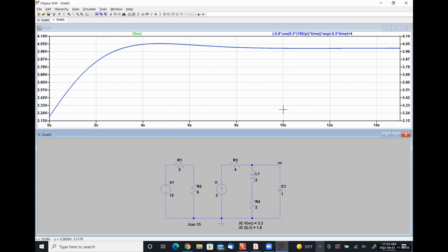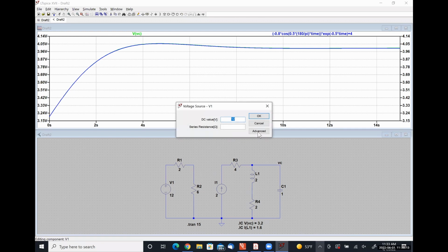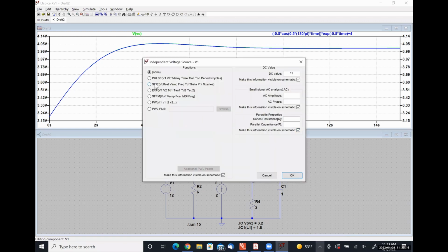Does Spice have an actual cosine function, or do I just have to change? You have to change the phase angle. If I was going to assign these little wave functions, they have like a phi, theta, delay. Phi needs to be 90, correct? Negative 90.